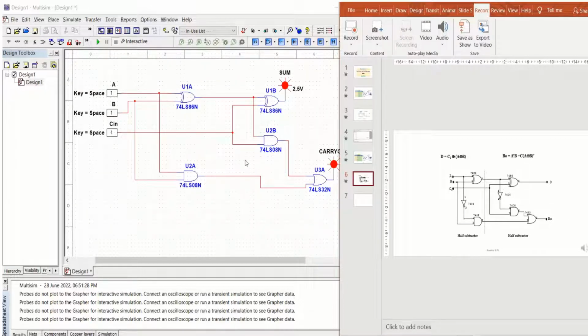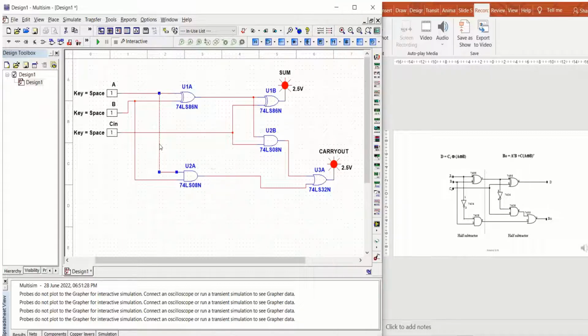So in comparison, we can just say that the two NOT gates have been added to the full subtractor with respect to the borrow expression. Now let us make out those two NOT gates. So this one, I need to add one NOT gate over here, and here I need to add one NOT gate. Right, so for the easiness, let me just drag it a little bit down so that I can easily place a NOT gate over there. Right, so I can also make it a little bit back. Fine. So now let me select the NOT gate.